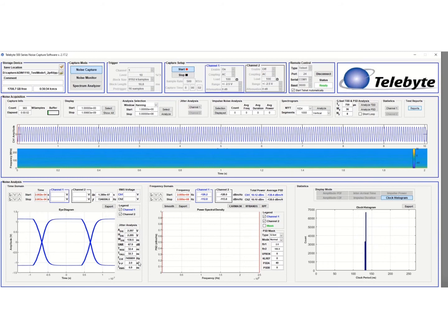The clock frequency is 7.499891 megahertz. And then the jitter peak to peak value is 2 nanoseconds, what we're measuring. And then the RMS value of the jitter is 0.9 nanoseconds. The peak to peak jitter must be less than 10 nanoseconds in order to pass. So we're passing with a fair amount of room. Analog Devices has done a good job on this.